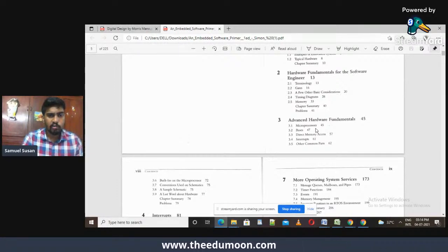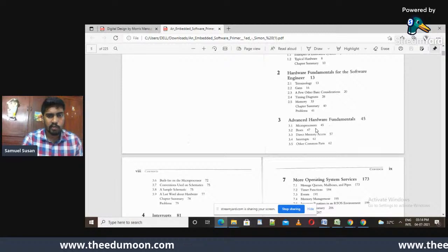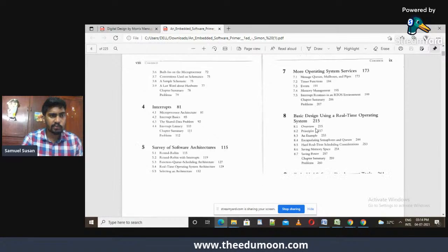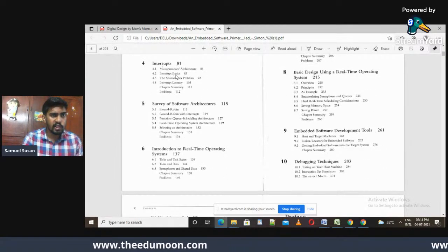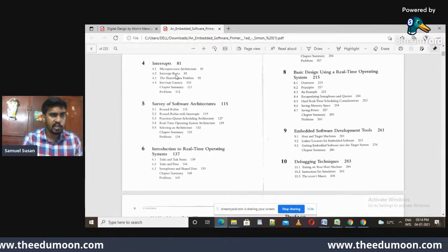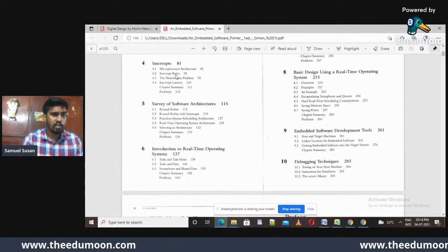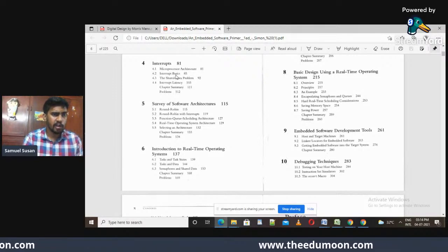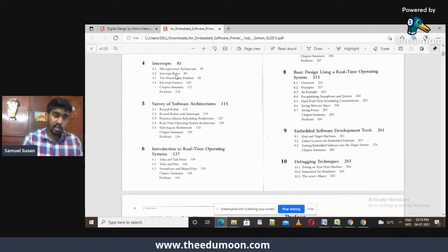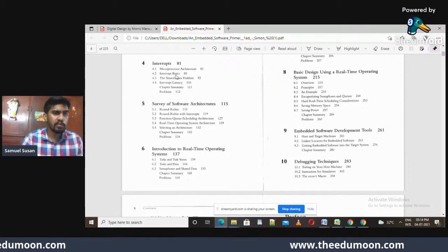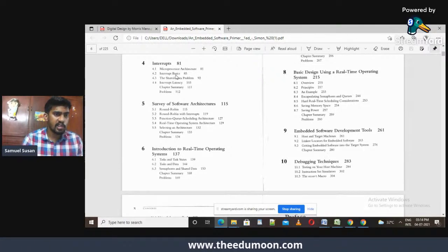So the important thing in the syllabus is the 8051 microcontroller, right? And from the next chapter, you can go with interrupts. So first we discuss whether it is useful to allow an interrupt or not. In many microcontroller applications or embedded system applications, there are always devices that are interrupting the system. So if you completely disable the interrupts, what happens is if there is a task having priority, that is not allowed any time sooner because the other lower priority tasks are executing currently. So interrupts are always allowed.